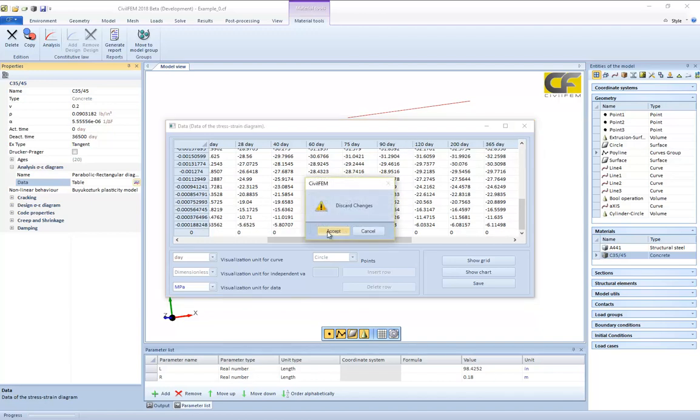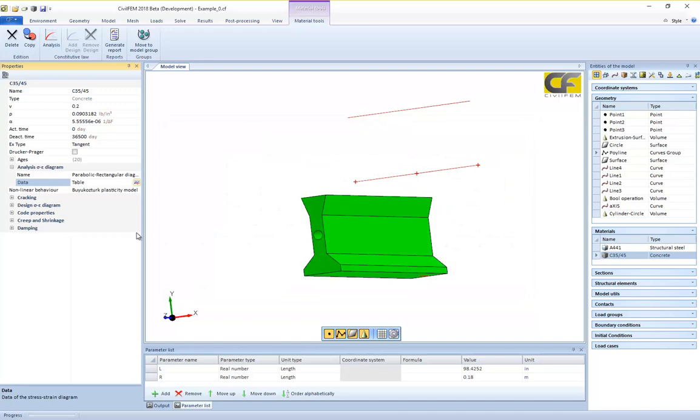For the non-linear behavior of concrete, we have these three models: the Drucker-Prager plasticity model, the multilinear elastic model and the isotropic plasticity model. So in this case, we can work with different parameters to obtain the correct behavior of our concrete plasticity model. But we will work with the default case, which is linear.